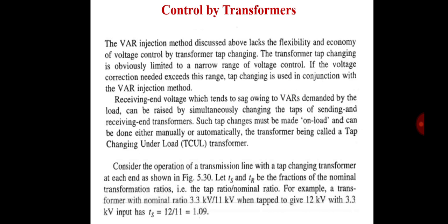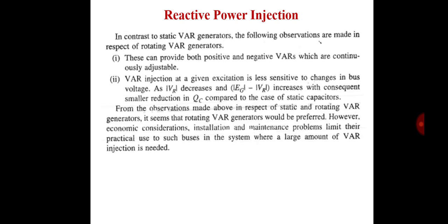From the observation made above in respect of static and rotating VAR generators, it seems that rotating VAR generators would be preferred. However, economic consideration, installation and maintenance problems limit their practical use to such buses in the system where a large amount of VAR injection is needed.